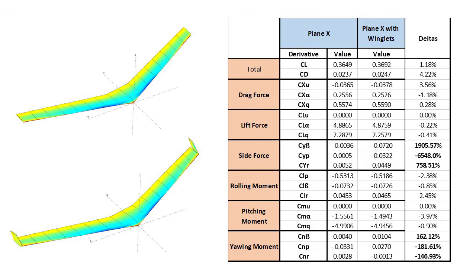It's clear that this quick design needs some careful adjustments to ensure that the directional stability and dynamic modes of Dutch roll and spiral are sufficiently damped, but that's exactly why I wanted to show you this list of raw stability derivatives to demonstrate what to look out for and what to think about when things change, and how to determine if the change is anticipated, unanticipated and acceptable, or more importantly, unanticipated and unacceptable.